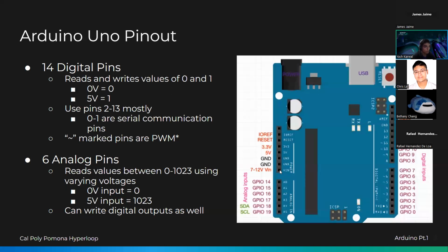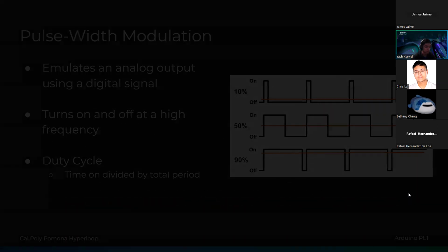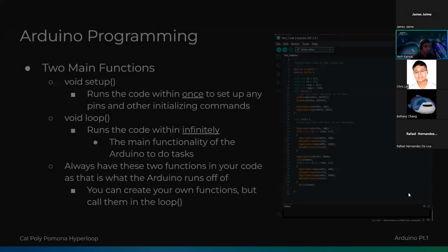So you can do a little bit more with this one, but again, be careful. I've driven a motor that draws 4 amps from the V-in pin when I was first experimenting, and the Arduino got pretty hot and was starting to smoke. So again, power requirements are a must. Make sure you know what kind of power you're using and how much you're drawing.